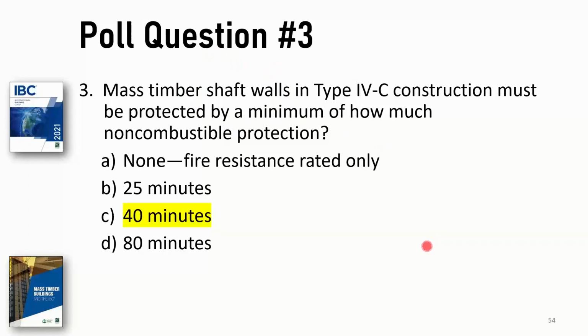The 80 minutes would be applicable to, well, let's see, would it be applicable? Think about this. Where would that be applicable? That may be applicable in concealed spaces. Let me think about that a little bit. But anyway, 40 minutes is the correct answer for shaft walls. And how about the rating? Still has to be 2 hours, okay? 2-hour rated walls. So the 40 minutes is not all you have. You've got the 2-hour rating, typically for shaft walls above 4 stories, right? 4 stories or above.